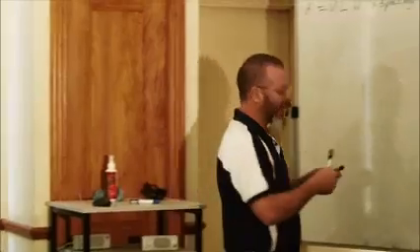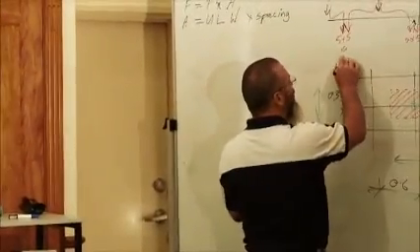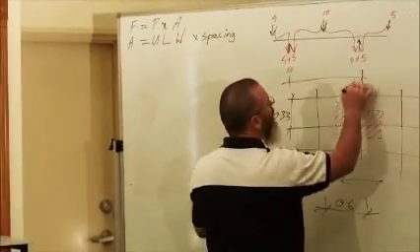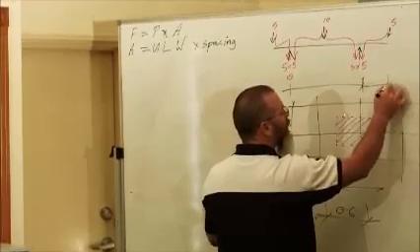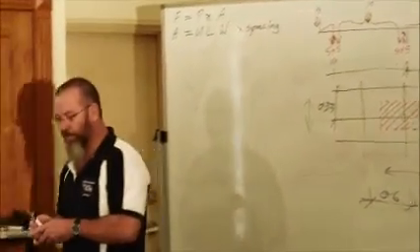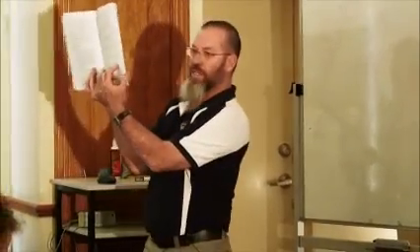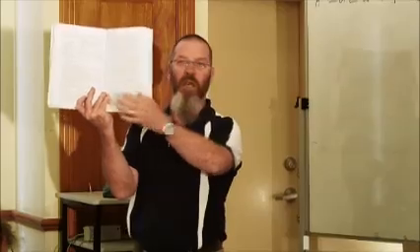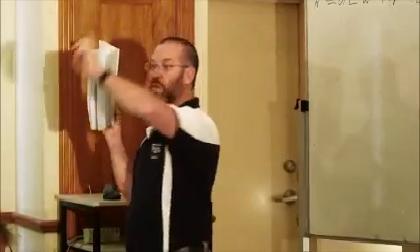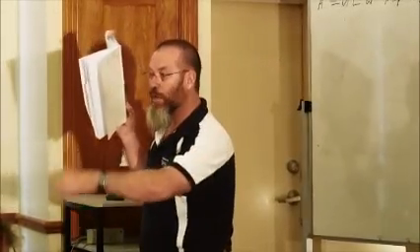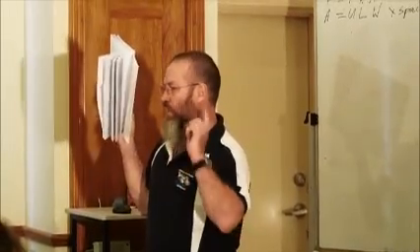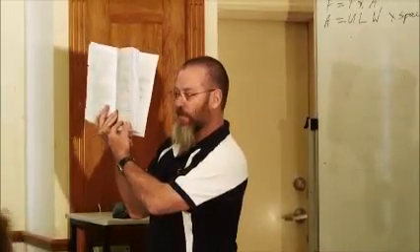So the load width in this case is half the distance between there and there, plus this. Have a look at that bottom diagram on page 171 or 169, depending on your book. Look on this side of that diagram. Can you see those ULW lines? It goes from half the distance between the wall frames, or half the distance between connections, plus the overhang. Can you see it there? See how it includes the overhang on the outside?